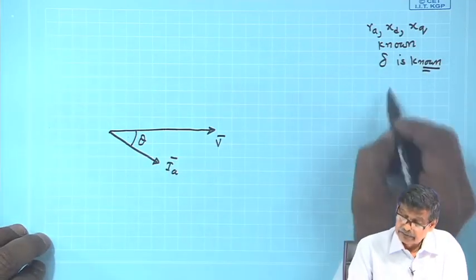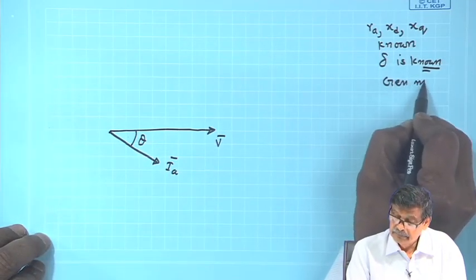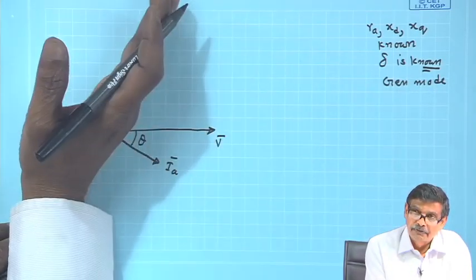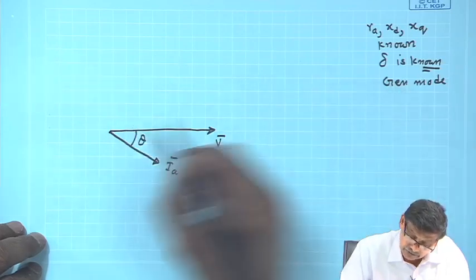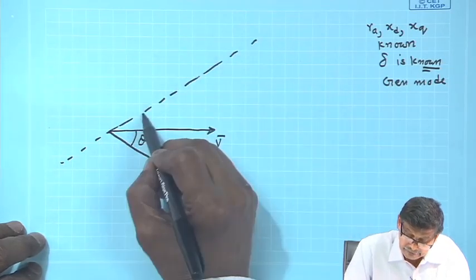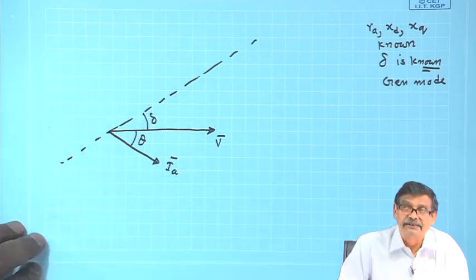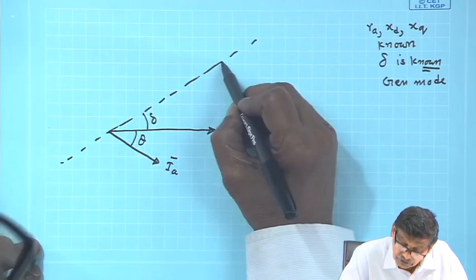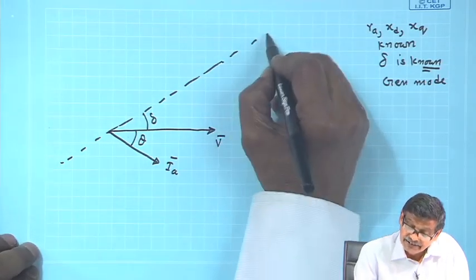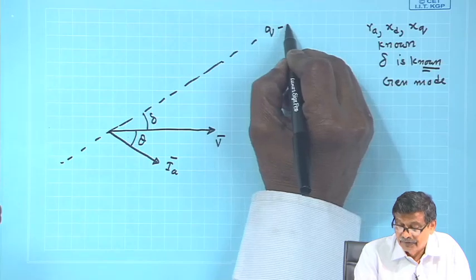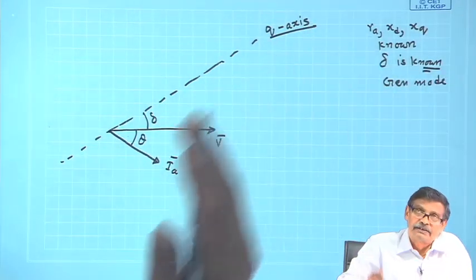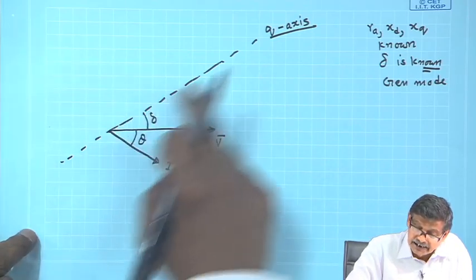And then it is generator mode. E f, which is on the q axis, must be above V. So, delta known. So, draw a line. Now, delta known, I will write delta here. Of course, I do not know where the E f is, but q axis is now known precisely. I know this is q axis. E f must lie along this line.